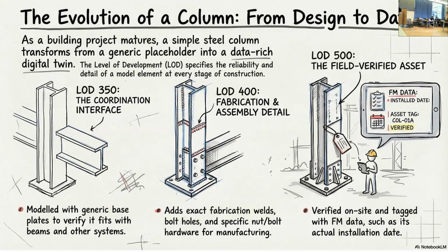But also, you put it in the beam bundle. So you torque it, you put the pencil mark on it, you can make sure that on that site, this pencil is only used for this torque number, and this machine is always calibrated for that torque. And you know that that machine is used, that pen is used, paint marker. That paint marker is used, then when you come to the site, you check, okay, paint marker, this torque, then you put it on the beam model. Then you know that it is torqued properly. Okay, you don't have to check it again.